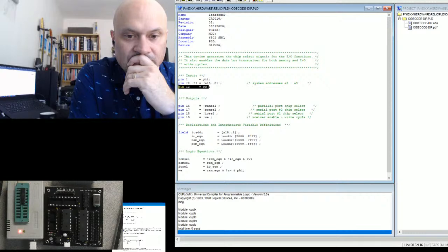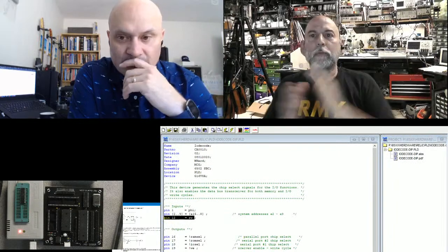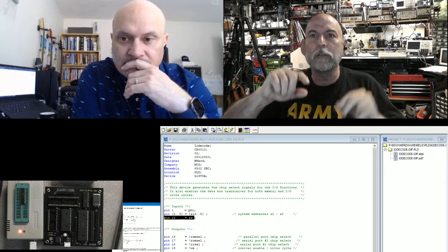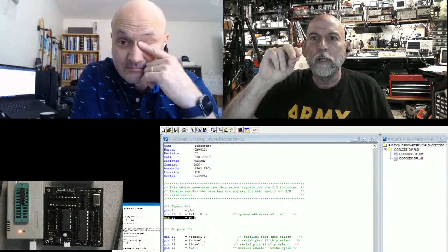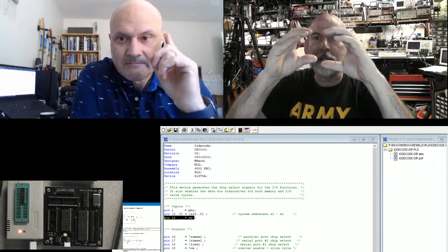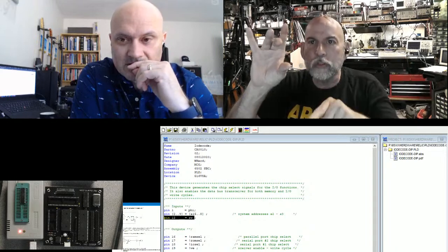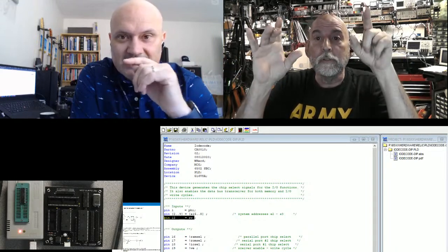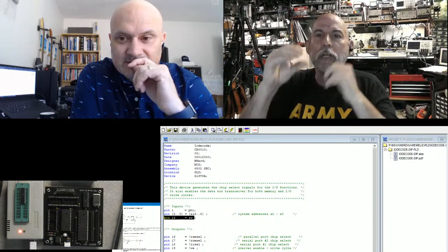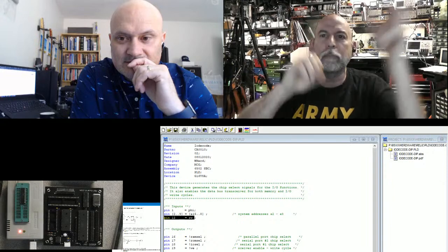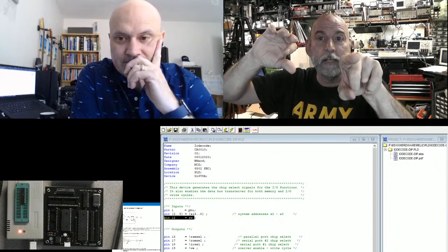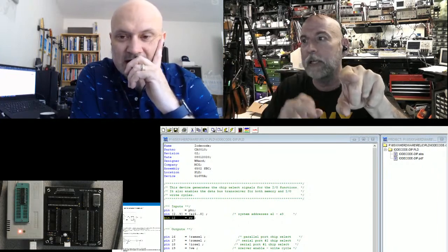The reason for, let me pull this down for a second. This is important. The reason why I need a gated write is if you just let the write line go low while the address lines are changing, you're writing all kinds of places in your RAM. You need the address lines to set up and be stable and then strobe it. We call them strobes, actually. Yes. The write strobe says addresses are stable inside the RAM. The address decode won't be flipping around, ruining the memory contents everywhere. He goes, I'm already stable. You mean that cell right there? Go ahead and write to it as the write line goes low.